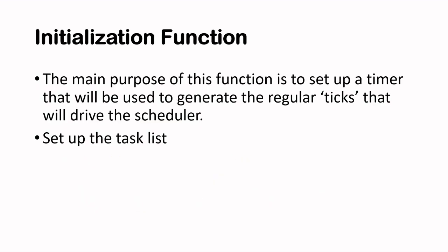arguments. The initialization function, the purpose of this function is to basically prepare or set the timer to generate regular ticks that is used to drive the scheduler. Another purpose of the initialization function is to set up the task list.